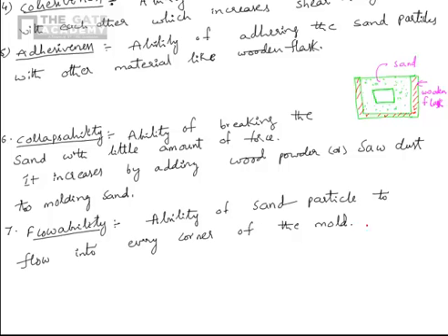The sand particles have to fill the entire space. If there are any gaps in the sand mold, or it is not filling properly, it will create defects in the casting.